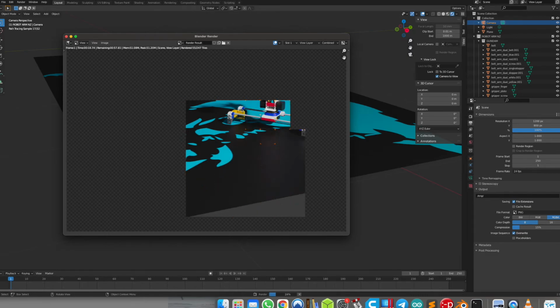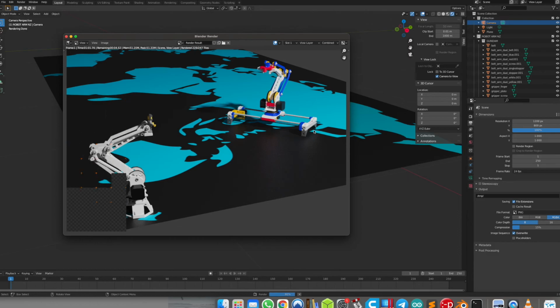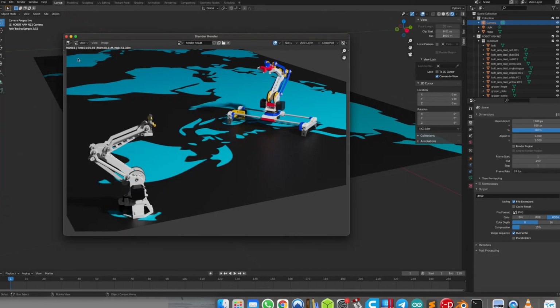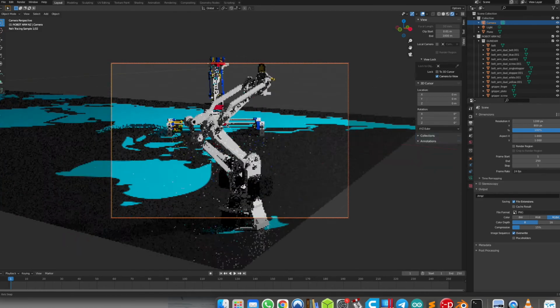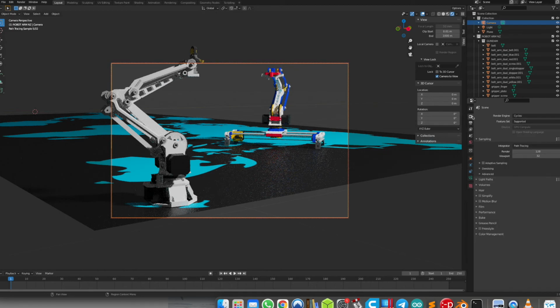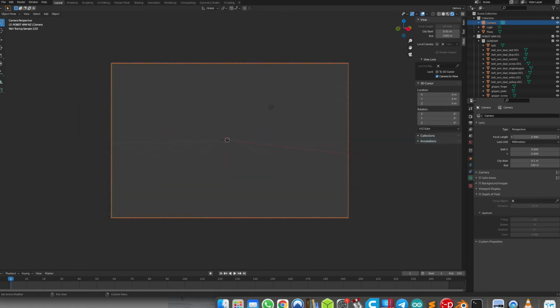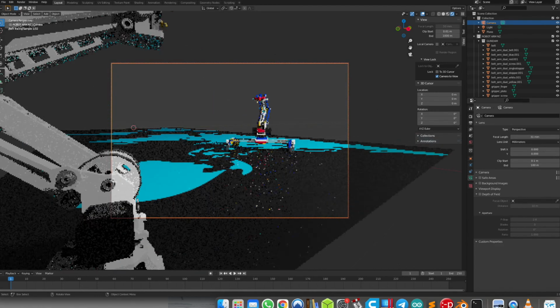Normally on a regular laptop it would take 1 or a few minutes to render a single image. So I've rendered the image and I'll save it into my computer. We can play with the camera focal length as well to achieve the effect that you want in your image. With the camera highlighted, we go into Object Data Properties, which is the green camera icon on the icon column. We can now slide around the focal length and view the simulated result on the workspace.